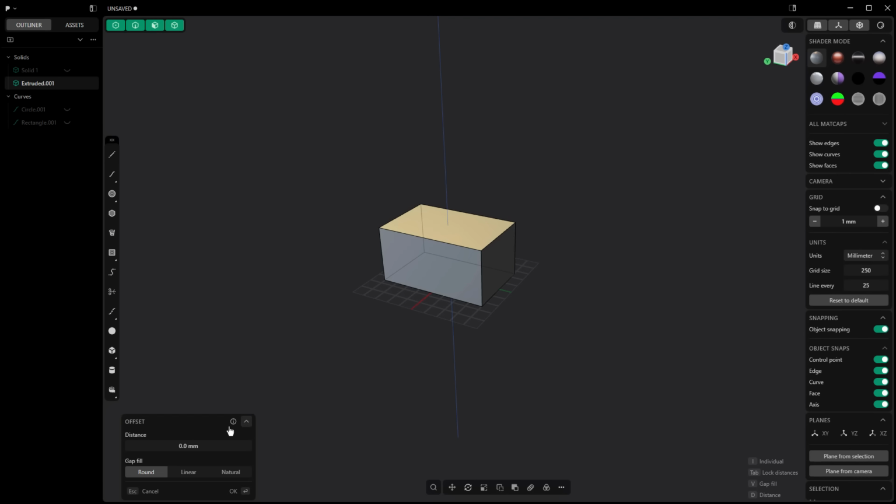And what this is going to allow me to do is offset this face. Now, this is where I find it much easier for us to do this with shortcut keys, because I find that going through that menu for things like offset to be a bit cumbersome. Whereas I'm going to hit escape and just show you. If I select this face and hit O, I can just pull that in relatively quickly. Now, another thing to note is that with our selection filters on, when all of them are on, I have to select the body first and then the face or the edge. That'll be 2 clicks. But if we have just face selection on, I can select the face, hit O, drag this in, and it's all relatively quick.